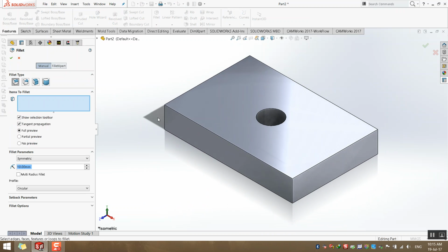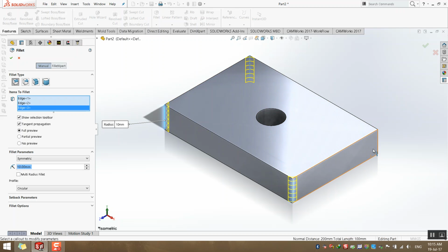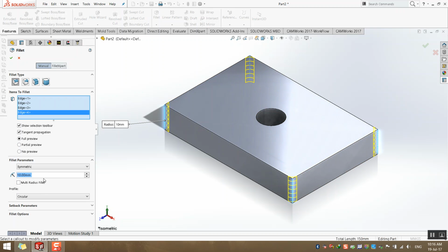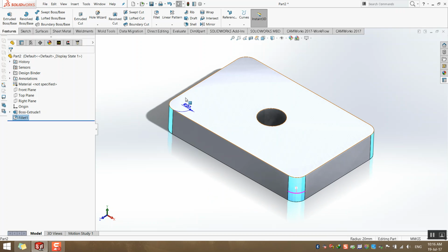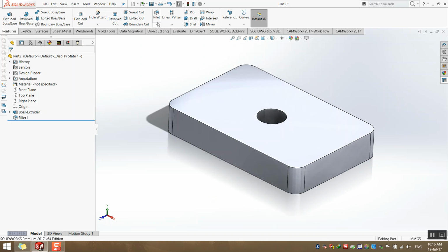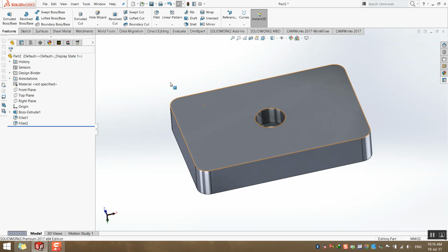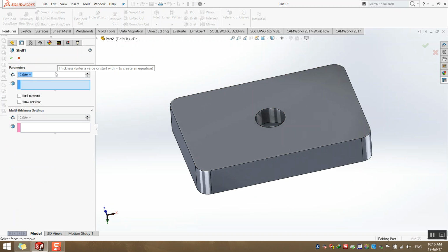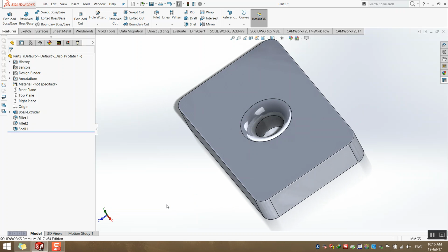Quick and easy. You can fillet corners with a specific number you need, radius 20. Also you can do that. And finally you can apply a wall thickness of 2 millimeters. This model has been created in minutes, or even seconds if you are practiced.